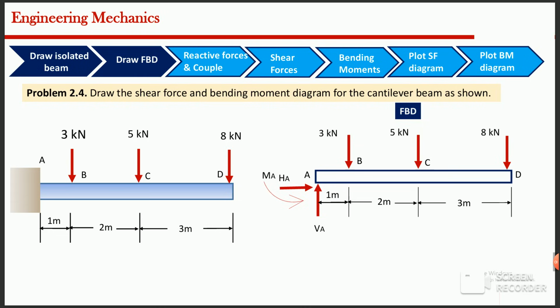Next, we include all the applied loads exactly as shown in this problem. The distances between the loads are also marked carefully because they will be required while calculating moments. This completed free body diagram becomes the basis of applying the equations of equilibrium.